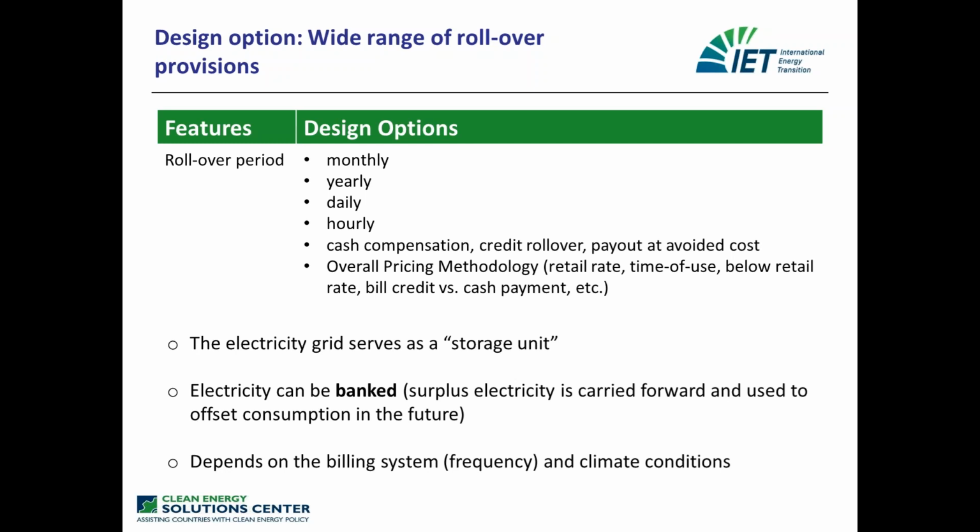So you only really want to avoid any excess that you have beyond the month, for instance, in order to lose this electricity. So instead of installing, let's say, a 3 kilowatt system on your rooftop, you decide that you only install a 2 kilowatt system on your rooftop, because this will allow you to maximize your self-consumption and to decrease as much as possible any influx of excess electricity into the grid.